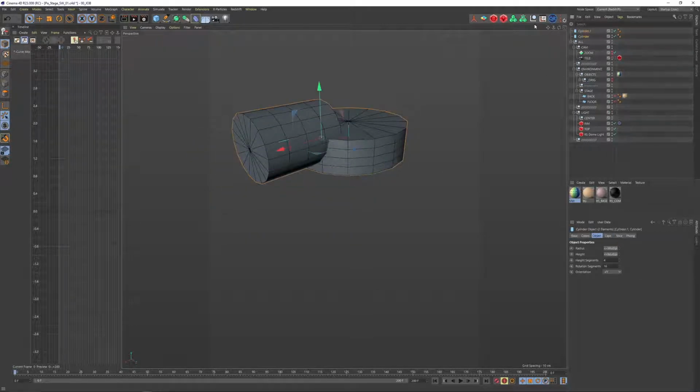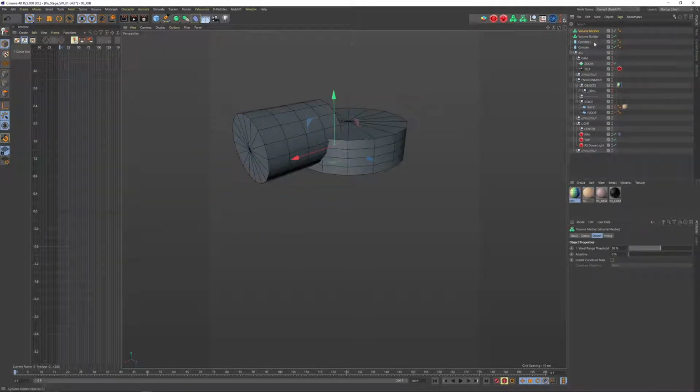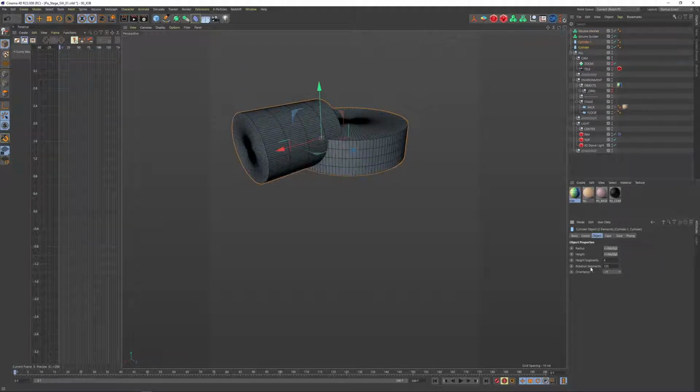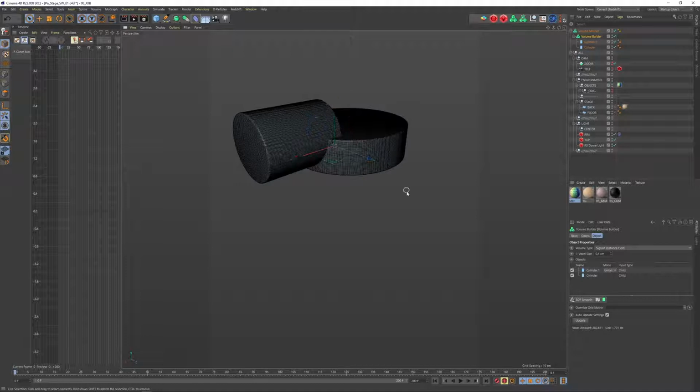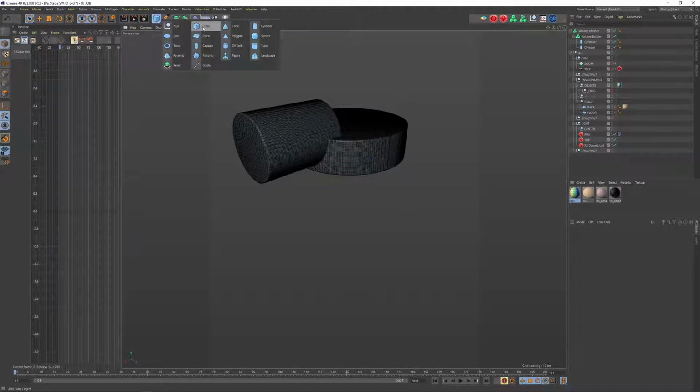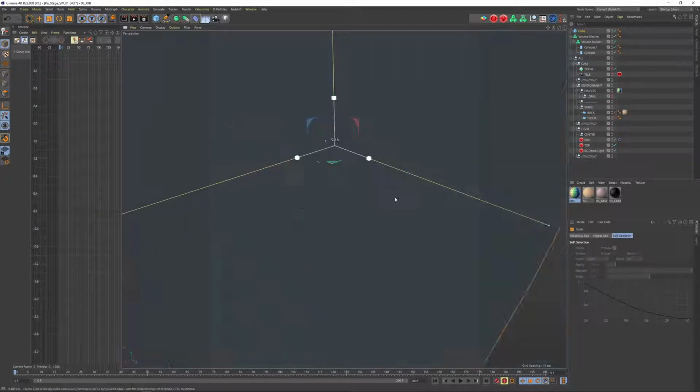So then we will use the volume builder and the volume measure, and if we use them, we'll always need more substeps, so we'll get a smooth interpolation. So therefore I'll select these 2, put them in the volume builder and the builder into the measure, and in this case I need a voxel size of 0.4. I already tested that.